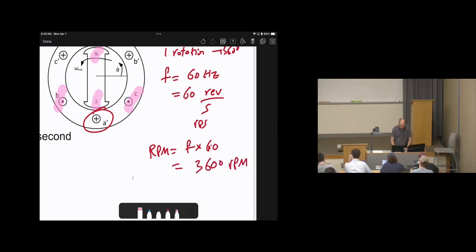As a result, I mean RPM, no matter if it is uppercase or lowercase, I'm making them uppercase. For the two-pole generator, in order to produce a 60 hertz frequency, it needs to rotate at around 3,600 RPM, and this speed must be fixed. If it is not, it will produce a different frequency than 60 hertz. In other words, the frequency and the speed of the generator are very related to each other. The speed of the generator determines the frequency.